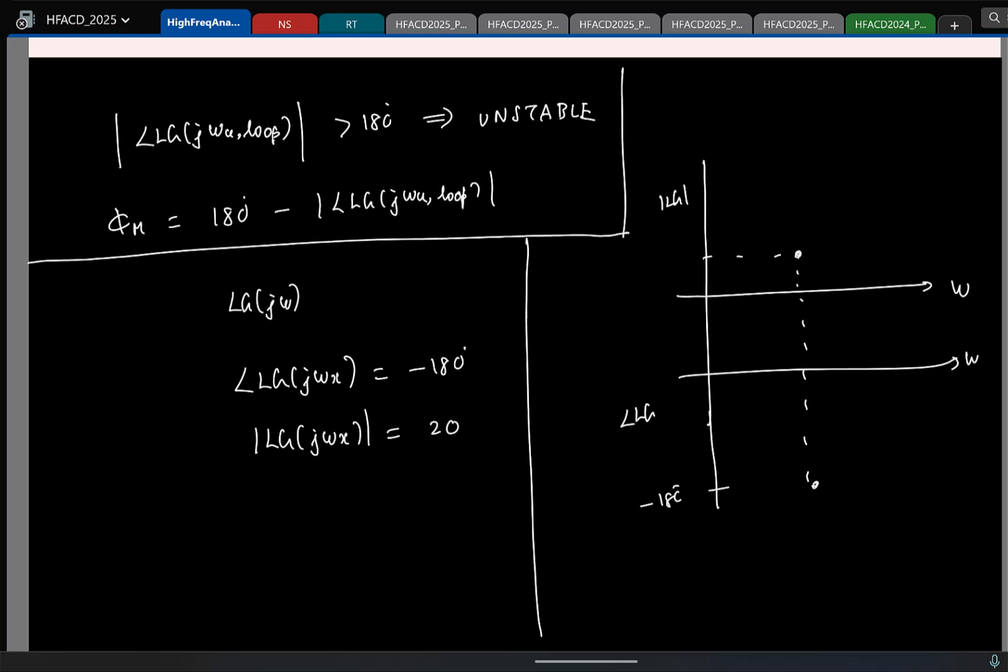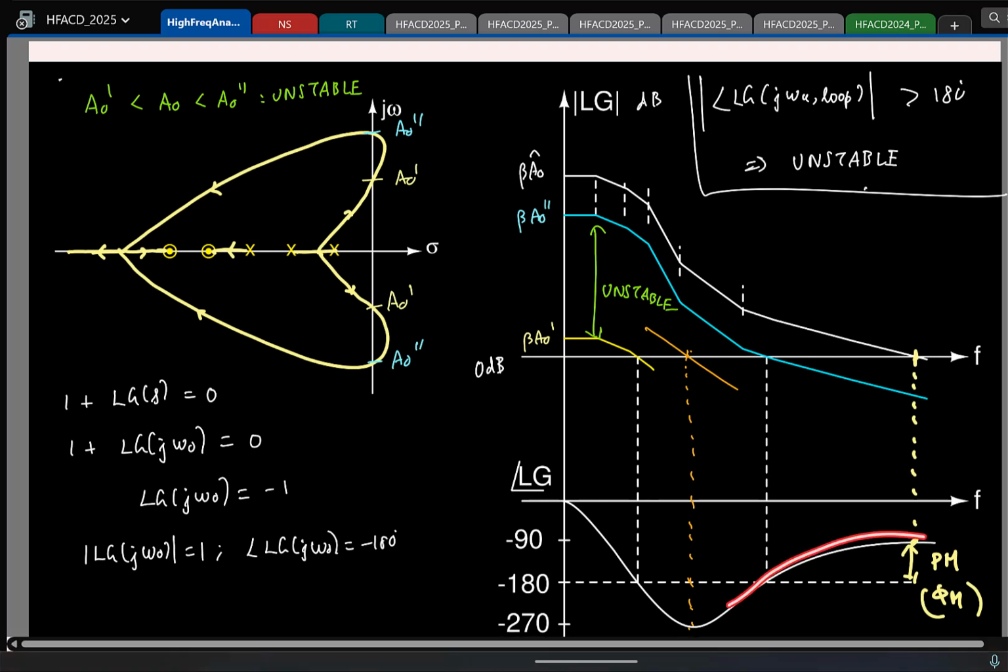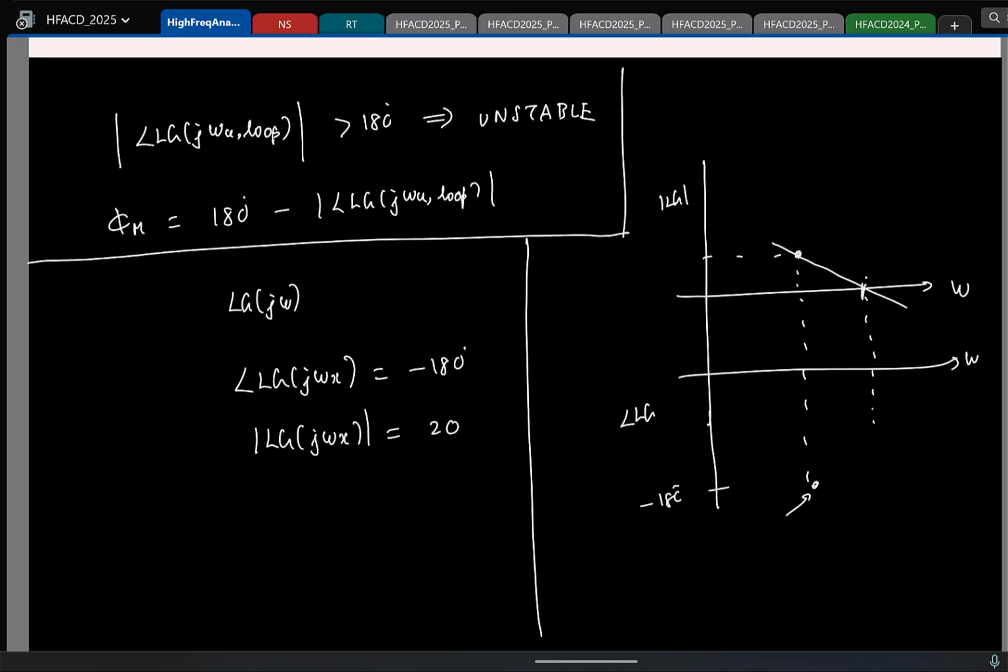Right? One thing is for sure, let us say the gain is dropping at high frequencies. So I should check the phase at this point. I just know the phase at this frequency. Can you make any comments about the phase at this frequency? Yeah, it can go up or it can go down. If you have left of plane zeros, that's what we saw, right? The phase was actually going up because we had the left of plane zeros. So here you can have two possibilities. It can actually go up and nicely become stable, or it can also go down, right?